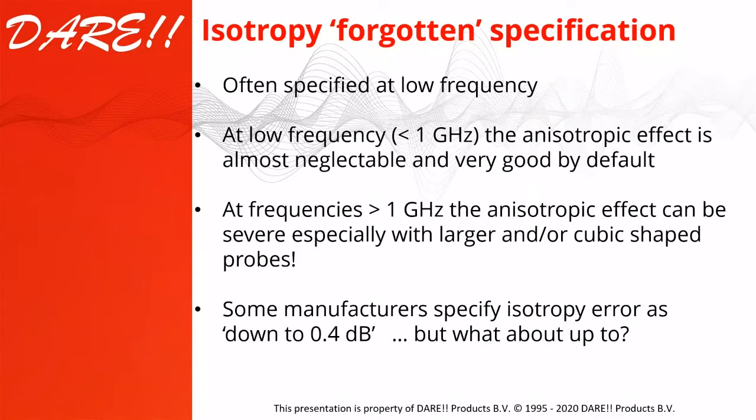And it's certainly the case if you have a cubical probe. A cubical probe, I already said before, you will have the eddy current effects, which will also give a disturbance field. So you will see at higher frequencies, the error of isotropy will increase. And that may also be the reason why until now it's very often specified at low frequencies.